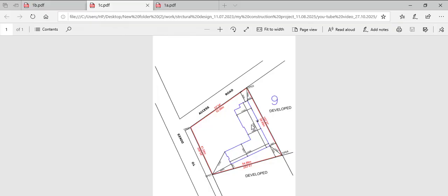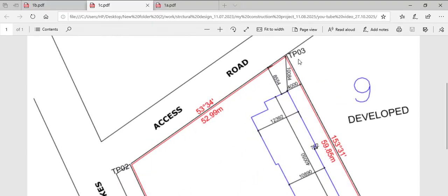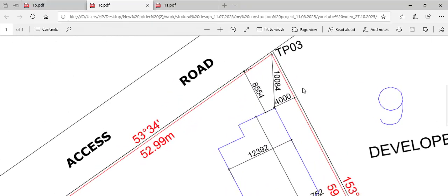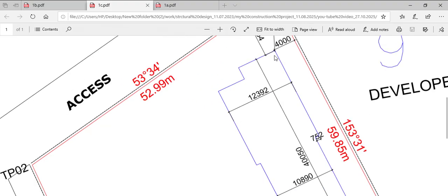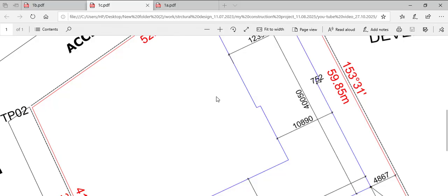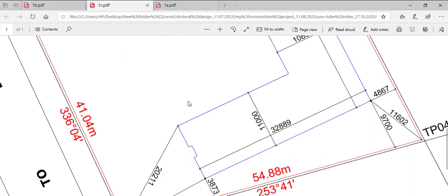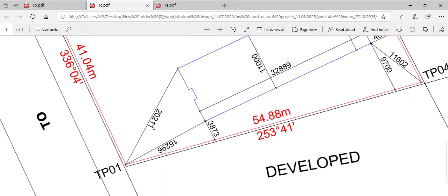But on getting to site, when we did the survey work, we found out that the plot was smaller than what the architect proposed. So my own advice in setting out is to get a surveyor to actually determine your plot size.